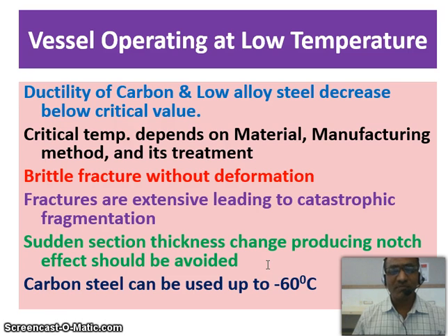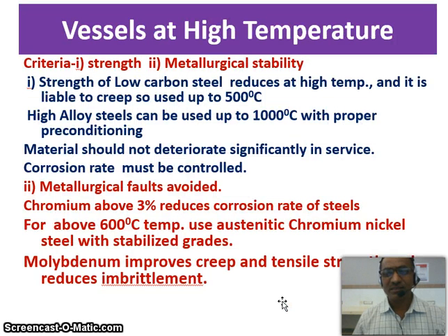For such type of application, for the equipment to be operated at sub-zero temperatures, carbon steel is a suitable material and that can be used suitably up to minus 60-degree temperature. When vessels are subjected to high temperature, the criteria of selection of the material normally is its strength and its metallurgical stability.